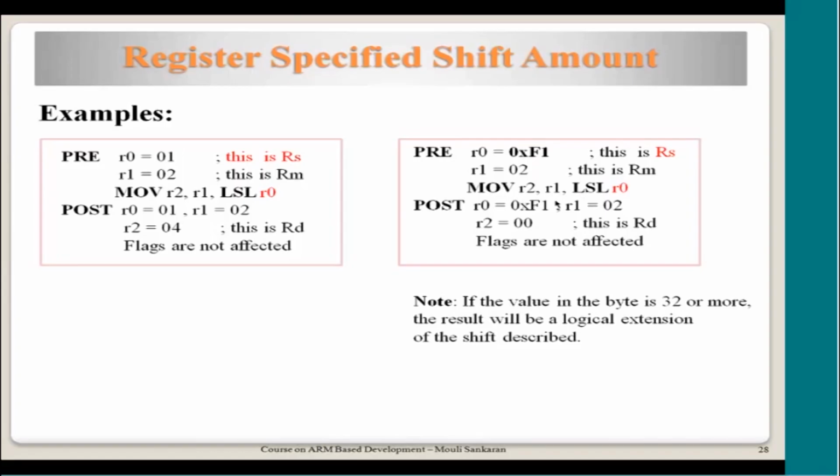When RM is copied, the R1 value happens to be 0 2 to start with, but once it does a logical left shift, it will be filling it with all zeros. So effectively it will be performing a shift operation so many times. But actually inside the processor, there is no point in doing that shifting blindly more than 32 times, right? So it will effectively give you the value you are likely to get when you do this many times, and then it will reflect the value.